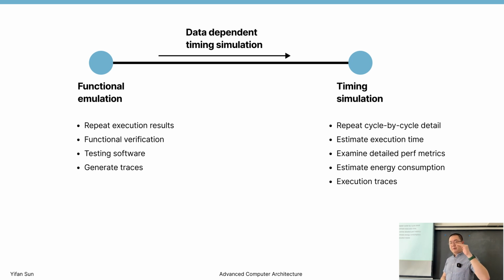So these are the memory locations I need to access in this order. Then you use this trace to feed into another cache-only simulator that only cares about the cache. In that case, although it's not the ideal scenario, it can still provide you some information, and it can be faster than running a timing simulation that considers every component in your chip.